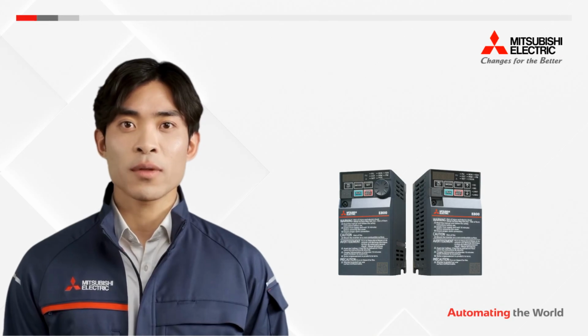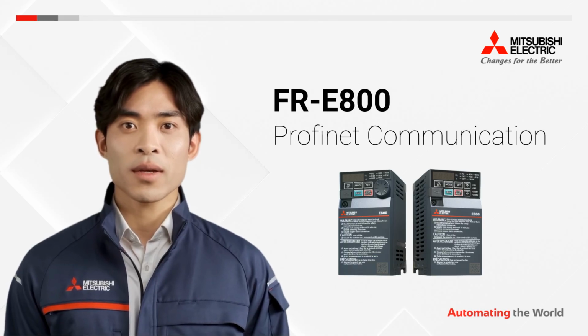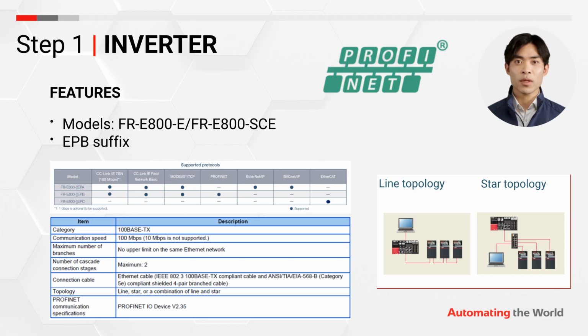Welcome back to this course, where we'll be talking about Profinet communication with inverters for the FR-E800 range. The models suitable for communication in Profinet are the FR-E800E or the FR-E800 SCE, if the safety function is also required. It is essential that both have the code ending EPB. The table shows the various Profinet protocol data, such as communication speed, type of cable to be used, I/O device category, and possible network topology, both inline and star.